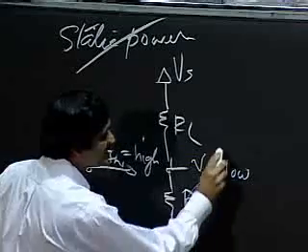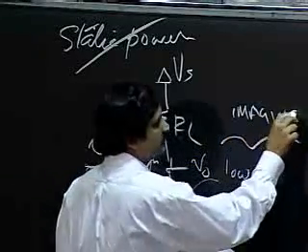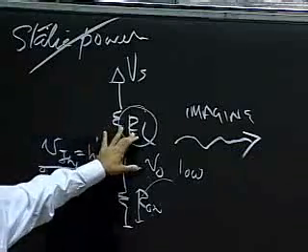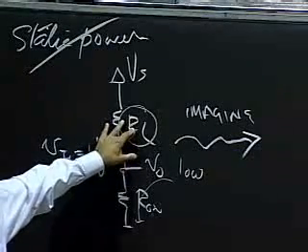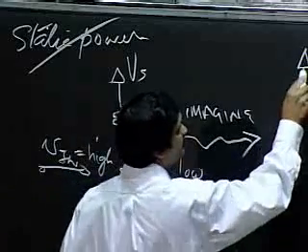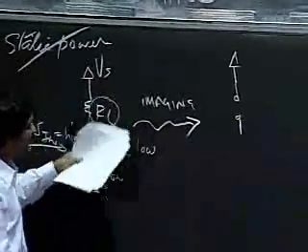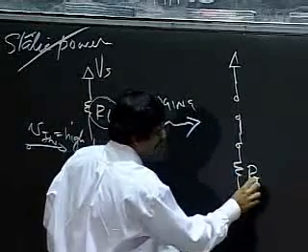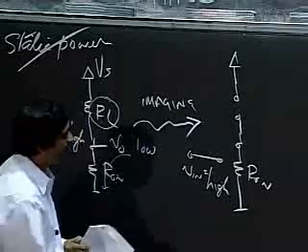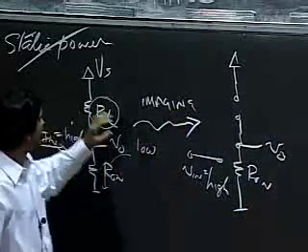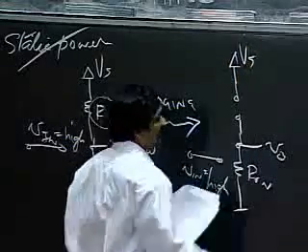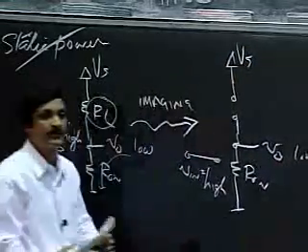Think about this situation here. The insight is, imagine if I could do the following. Imagine if I could somehow magically elevate RL to be a very, very large number, so high as to make the power really low, only in the situation when the input was high. Imagine I could open circuit this guy. So when Vin was high, instead of having an RL here, what if somehow I could make this RL become infinity? In this case, output VO would be low.